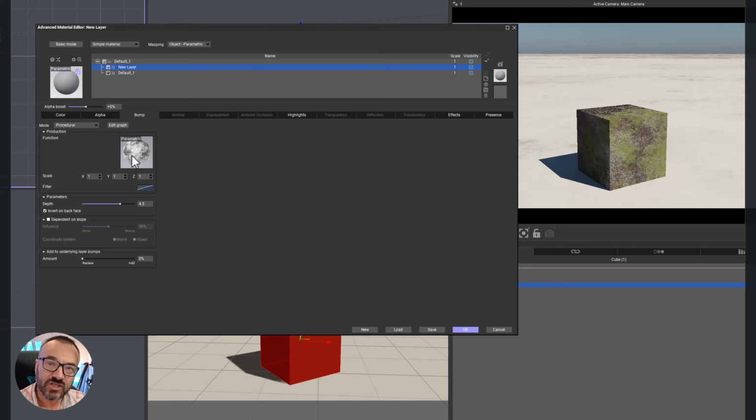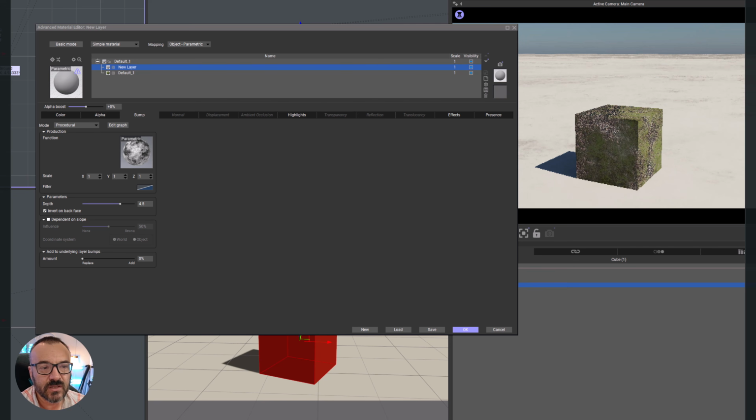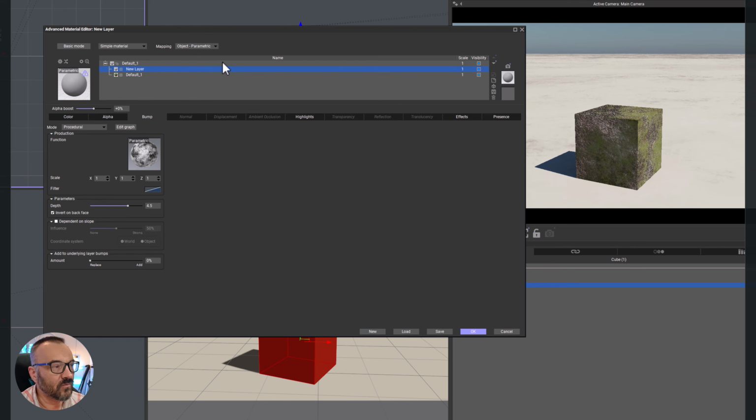Black will apply shadows down and white up. And it's not just applying dark and white this way. The engine works with calculating the light rays, how they hit and reflect. So the bump map will change if I rotate or adjust my object, and they will correspond directly to the lighting. So if you can see where we have shadows on the side with our light, let me move around,